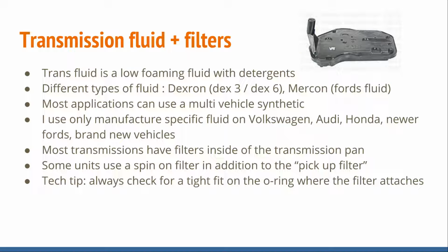But if you have a loose fitting seal, you always want to address that, because if we have a loose seal right here, the transmission fluid is down here rather than it sucking fluid through the filter and back up through the seal. We could suck air through there, and we don't want to do that.